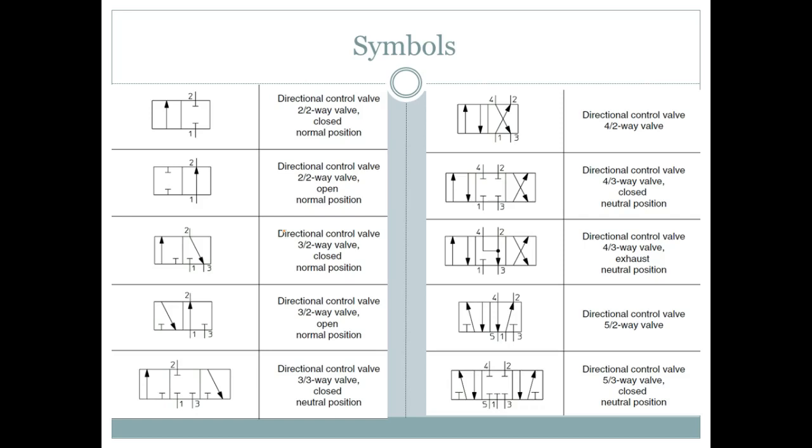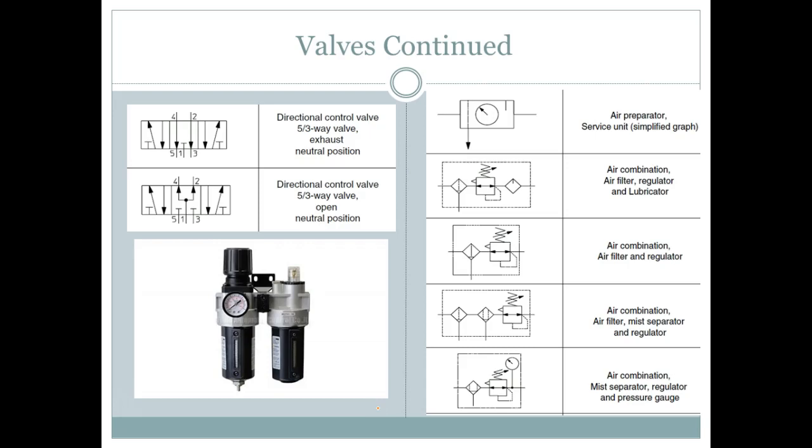So here they don't call it floating. It's the same thing, but they call it what? Exhaust neutral position. You see that? Yes or no? I'm right here if y'all wonder where I'm at. We're looking at the three position valves. It could be right here. This one right here, they call this a closed center or closed neutral position. You okay? This is a closed neutral position. That's a 3-position valve. And then this would be an exhaust neutral position. So what could you do with the actuator right here?